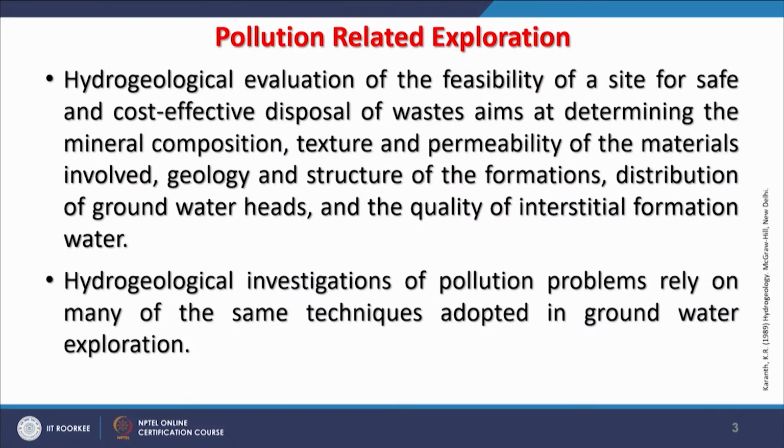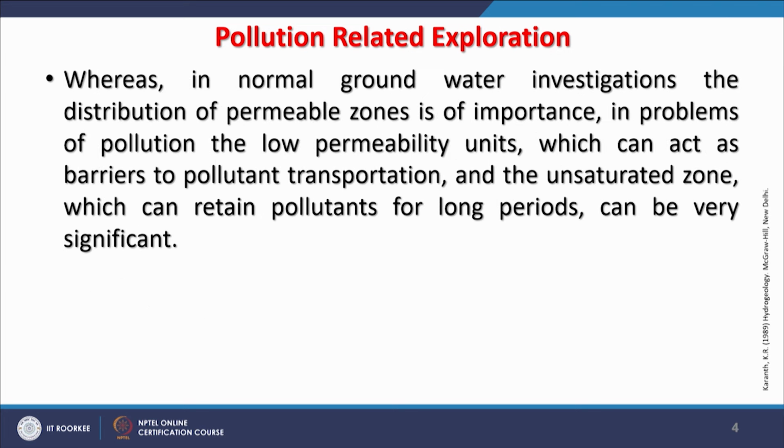Now, this is related to groundwater engineering, the pollution aspect, and substances which are being put either on the surface or in the drainage system. So, extensive hydrogeological investigations of pollution problems basically require almost the same techniques as groundwater exploration. That means we have to understand the complete characteristics of the formations, what kind of texture is there, what kind of porosity, what kind of permeability, and then sites can be identified for the disposal of waste.